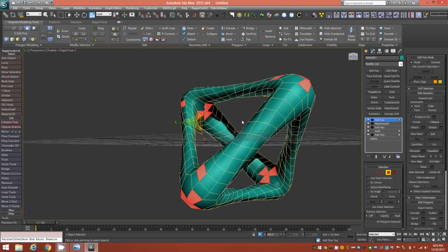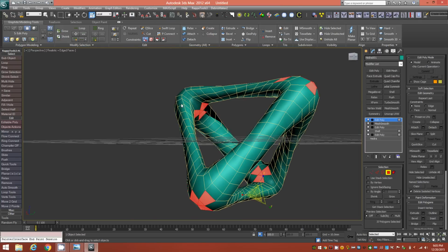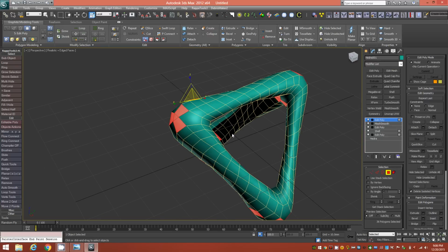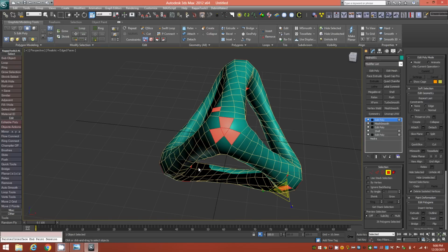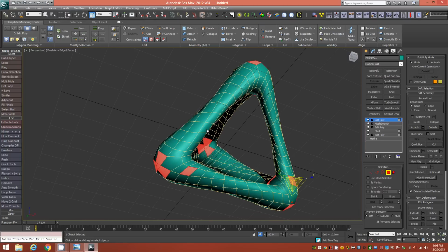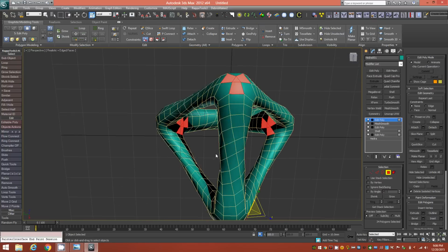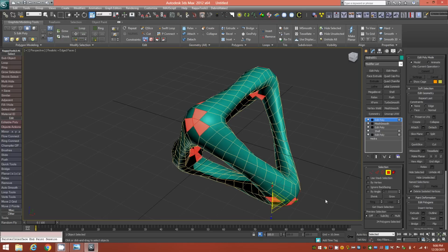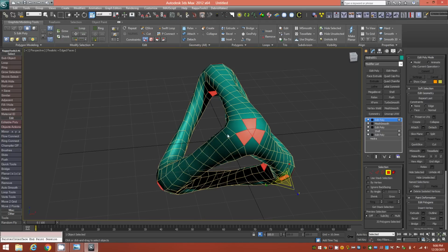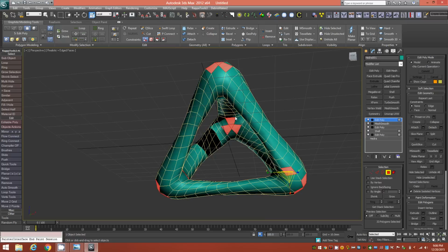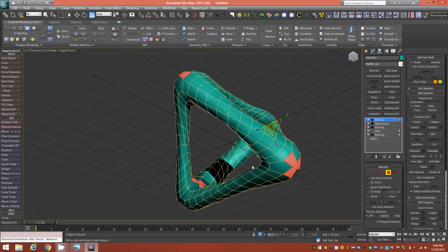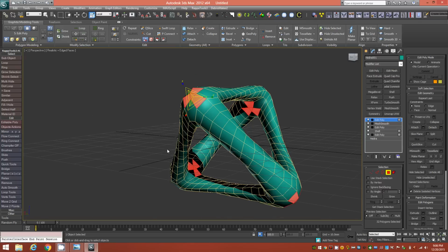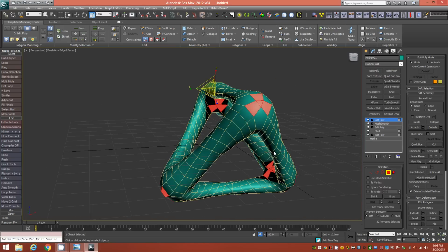But the reason is probably because these particular polygons were exactly the same as the ones I intended to select. Usually select similar is very intuitive, and you might not have this problem depending on your scene scale and whatnot. So just make sure that those random faces it may have grabbed are deselected.